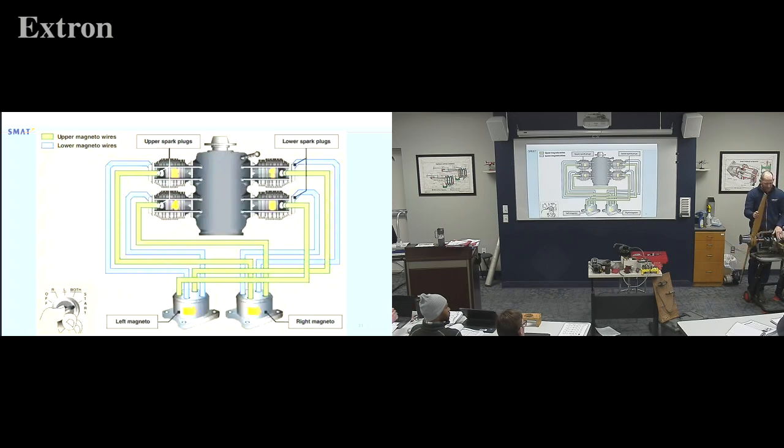So we get to the bottom, and once we get to the bottom or somewhere near it, Ryan's going to teach you in great detail the exact timing for your engine of when the valves open and close. I'm just using "at the bottom." In his class, it'll be how many degrees before or after bottom. But near the bottom, the exhaust valve opens up, and as the piston comes up, it pushes all that burnt gas and air out into the exhaust pipe, and now we're back to the beginning. So stroke 1 is intake, stroke 2 is compression, stroke 3 is bang, power stroke, and stroke 4 is the exhaust. It allows it back out.